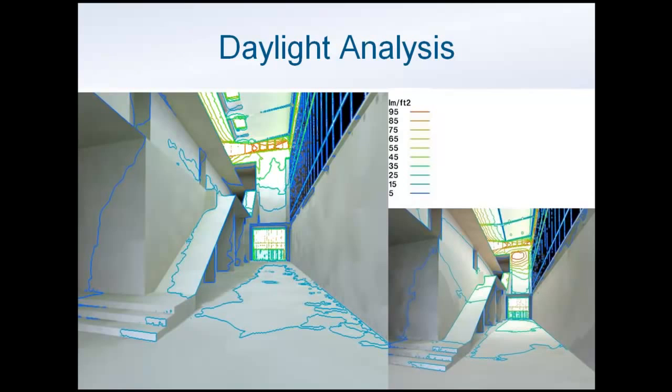So one of the things that we were doing with this daylight analysis was not only to get a feel for what it would look like, but to test proof of concepts of skylights versus tubular daylight devices, make sure that it had the architectural treatment that we wanted, and also to address potential maintenance concerns for the amount of roof penetrations and the potential for people inside the space to see debris on the roof, or whether it would create another requirement for maintenance on the roof that was not desired. As it was, we went with the skylight scenario, which is the image on the left-hand side, which was shown to have better daylight performance overall.